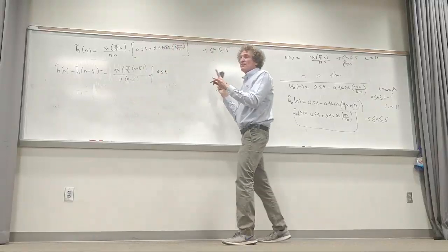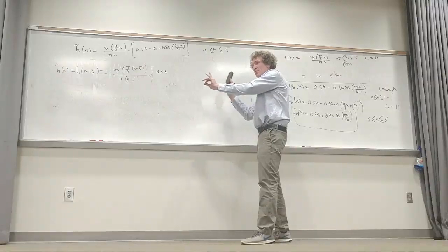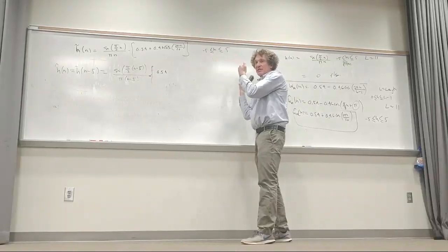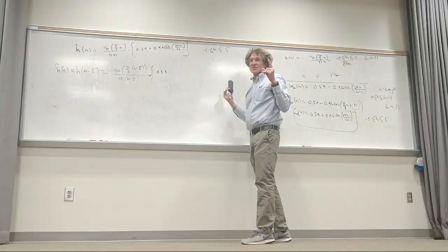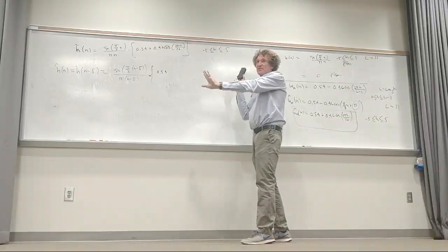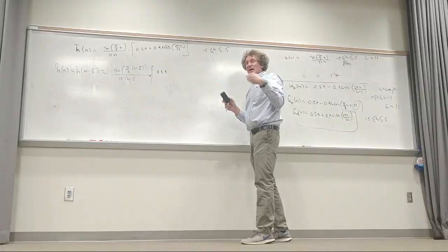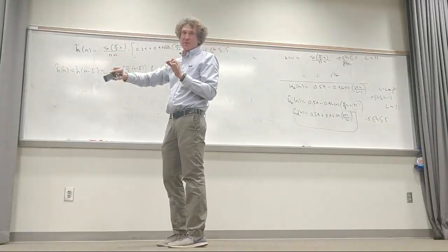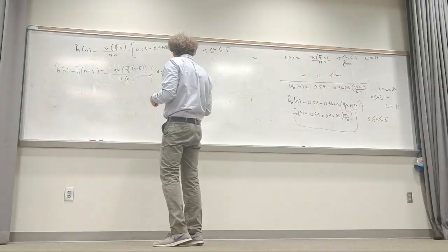Because a lot of times when they modify windows like this, they actually take the windowing function and move it back until it fits squarely over the impulse response that's not causal, and then they just multiply it out there, and then they shift everything. I know this sounds wacky, but it's sometimes not just one window that they use, and they want to get all the windows shifted to the point where the impulse response is actually recorded. Some of these things are driven by a lot of other things other than a simple response like this. We assumed it was a nice square thing, we're just taking a window on that. It can be an actual ripple effect and stuff like this. What he did in the book is something that is actually done.